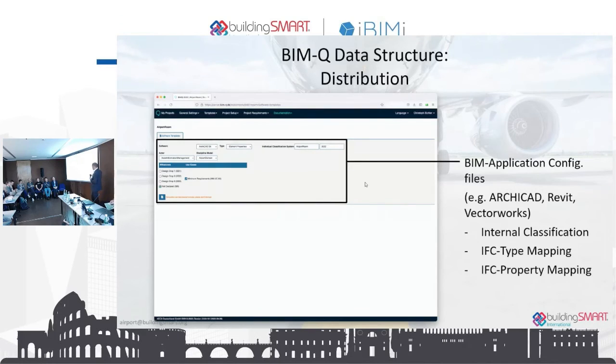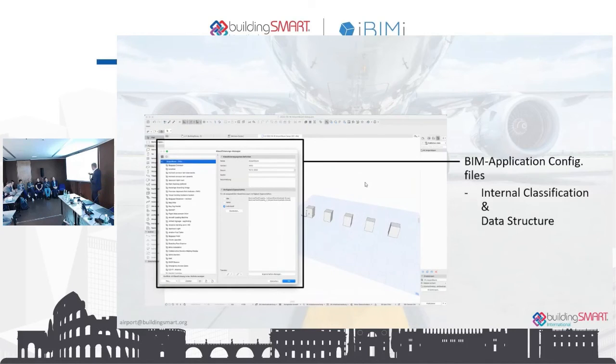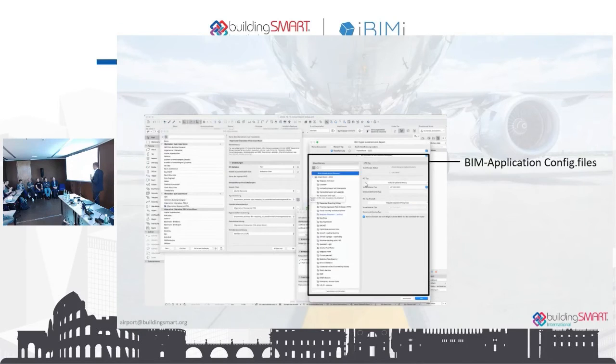This is only an example. We can hand over these declarations directly in a BIM application. In this case here, this is Archicad. We can use this declaration to declare objects. So this is a conveyor belt. This is a light mast, for example. This is a marking, an apron marking or something like this. So this was only a test to make sure that the declarations we hand over in the BIM application and the configuration files work completely fine and we can produce correct IFC files.